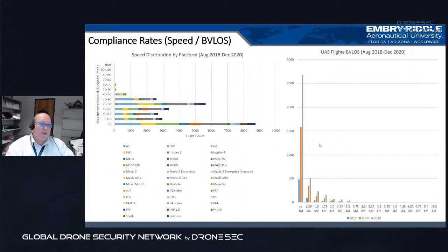One of the ways that we do this is we have the ability to identify the unmanned aircraft operator's launch location, and then we can measure based on the size of the unmanned aircraft and reverse calculate to what's known as 1 arc minute. 1 arc minute is a 60th of a degree and is largely considered to be the capability of the human eye to see at a maximum distance. Now, the FAA doesn't necessarily dictate what the visual line of sight should be, but if we compare that to what the capability of the human eye is, we should get a pretty good idea.